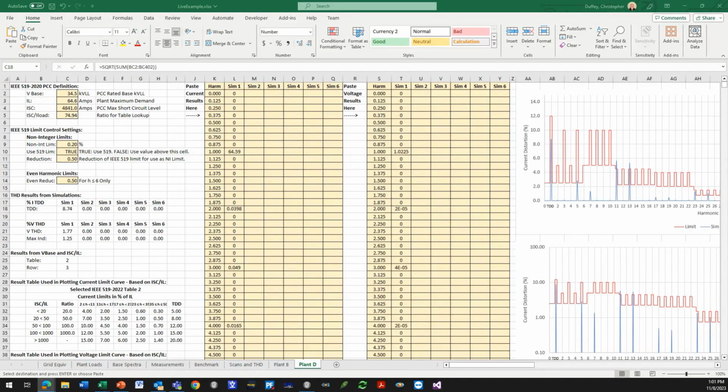For worst case simulations, what I typically do is set them all to 0. And then when I get my summed result back at the substation, if I have a measurement that I can compare it to, I'll see how far I'm off. And what I have done in the past is just lower their magnitudes.